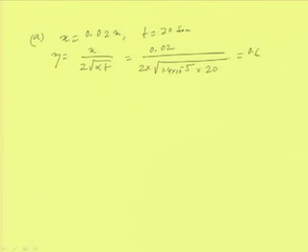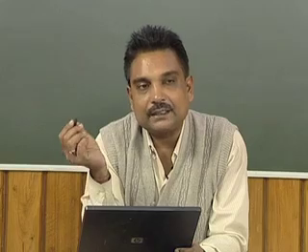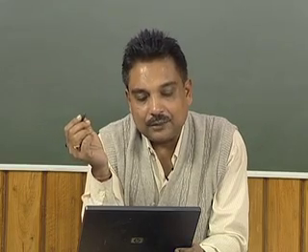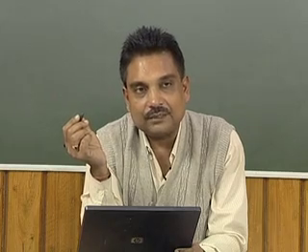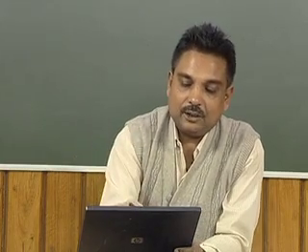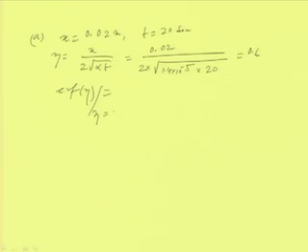Now, we have to find out the error function of eta. Actually that can be found out from the tables given in different texts and references. The error function values can be found out, and erf of eta when eta is equal to 0.6 is nearly equal to 0.6. So, just putting this value, what we get.